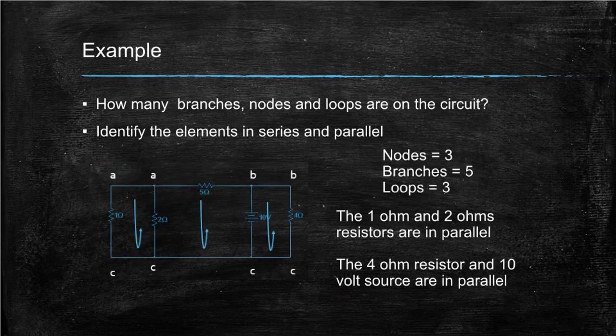Here's an explanation. There are 3 closed loops. There are 5 elements, meaning there are 5 branches. Before and after each element is a node, so put letters to it to make it easier. But remember, if there are no elements between any 2 nodes, those nodes are equal. Check your highest letter to see the number of nodes. In the circuit here, there are 3 nodes. Clarify your answer using the number of branches formula.